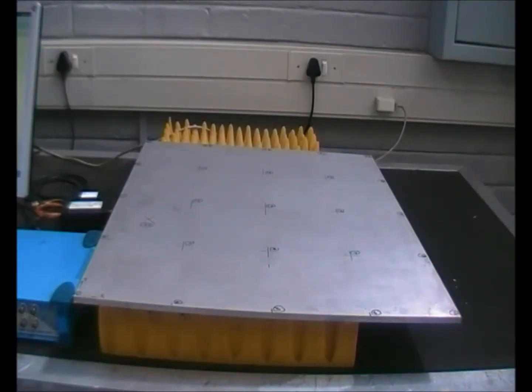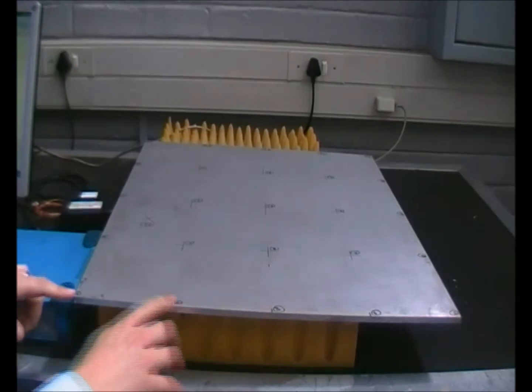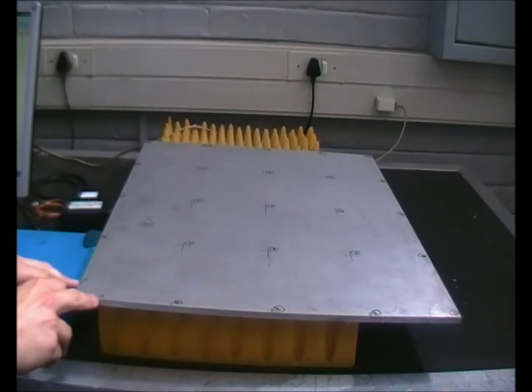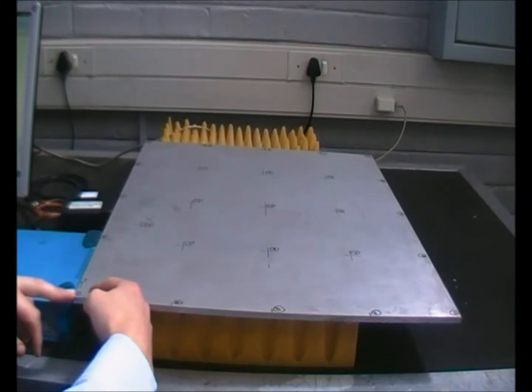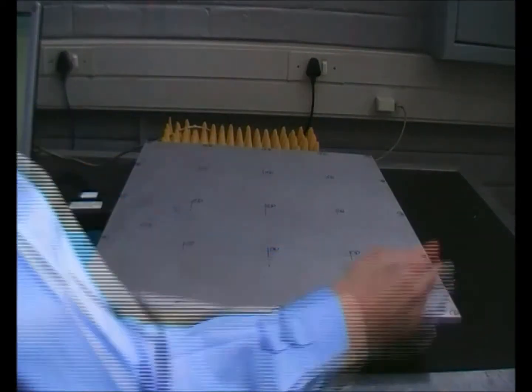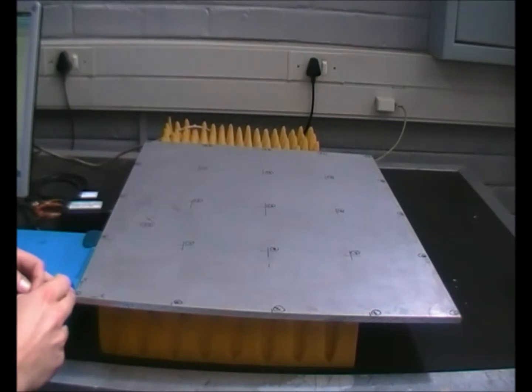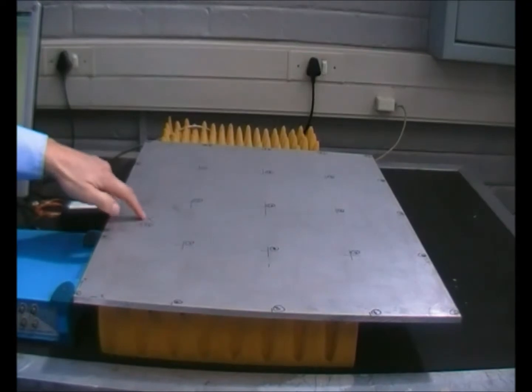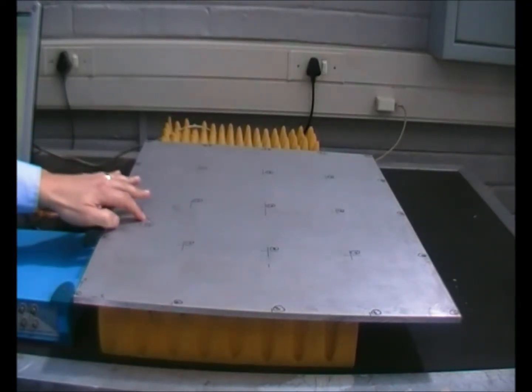Okay, so our first step is to define the geometry. Now, as I've mentioned, there is some preparation work that you need to do before you can perform the actual tests. If you look over here, I've already marked out all the points I want to measure on my plate, and I've also chosen my coordinate system with the origin here at point 1. I've defined a matrix of 5 points in the width and 5 points in the length, giving me a total of 25 points, and also another point, number 26, that I will use as my reference location.